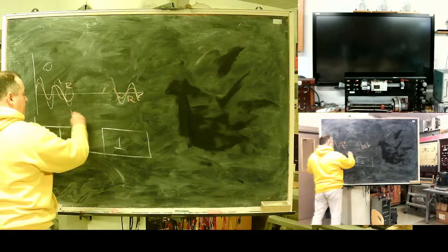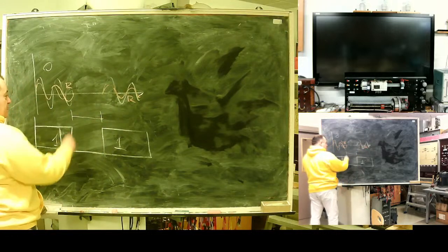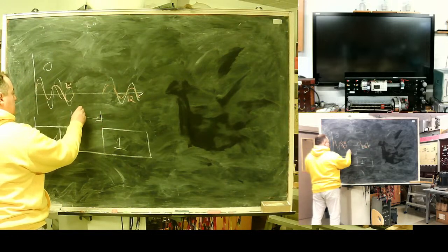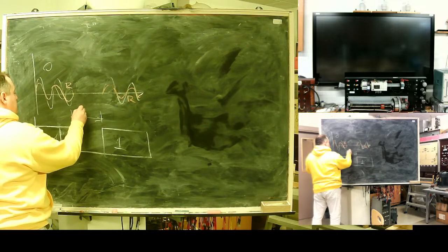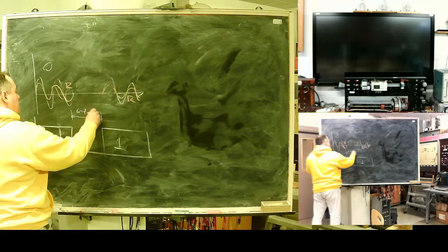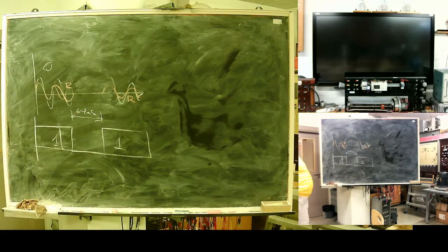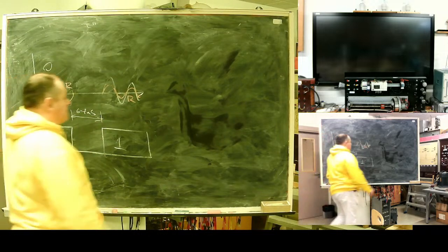If this gap is above 6, 7 milliseconds, it's an internal fault, we need to disconnect.